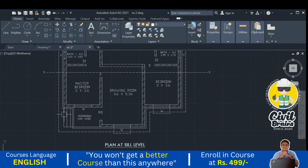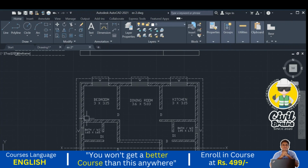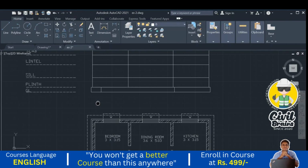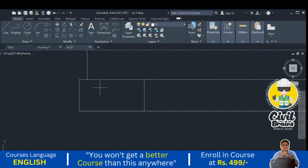We are using steps. Steps, from where are they starting? From this wall line they are starting. Okay, these are our steps from here. From here it is starting 0.15. As I told you, in the elevation the riser will be visible, in the plan the treads will be visible.